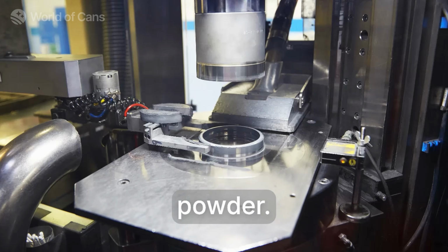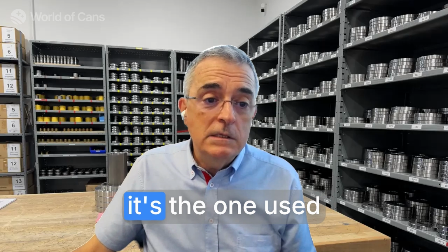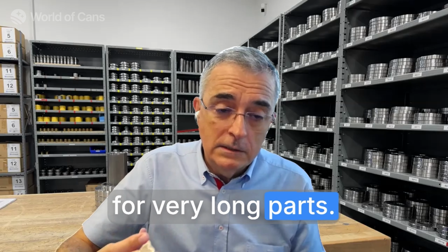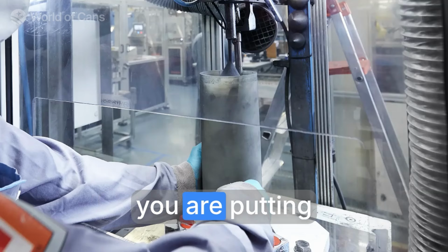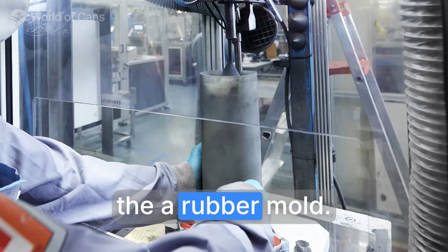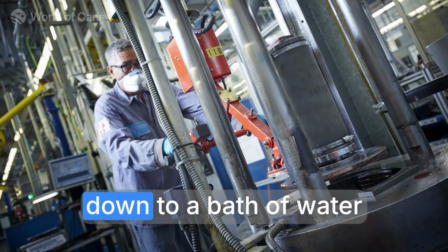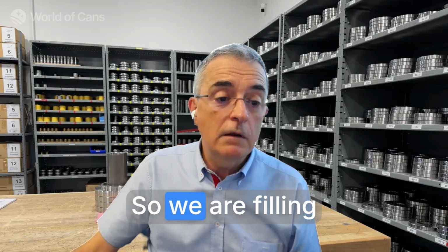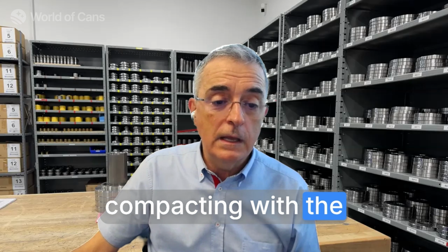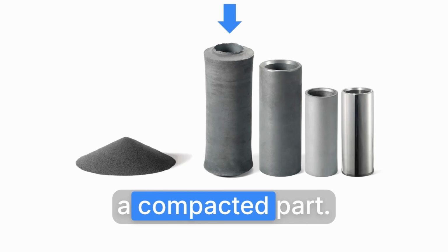It's just compacted powder. The other technology, that is the cold isostatic pressing, it's the one used for very long parts. This one is the one used for the punches. With this technology, you are putting the powder inside a rubber mold. This rubber mold is closed and is going down to a bath of water that you put pressure of water up to 1500 bars of pressure. So we are filling the mold, we are compacting with the isostatic press, and then you get a green body that is a compacted part.